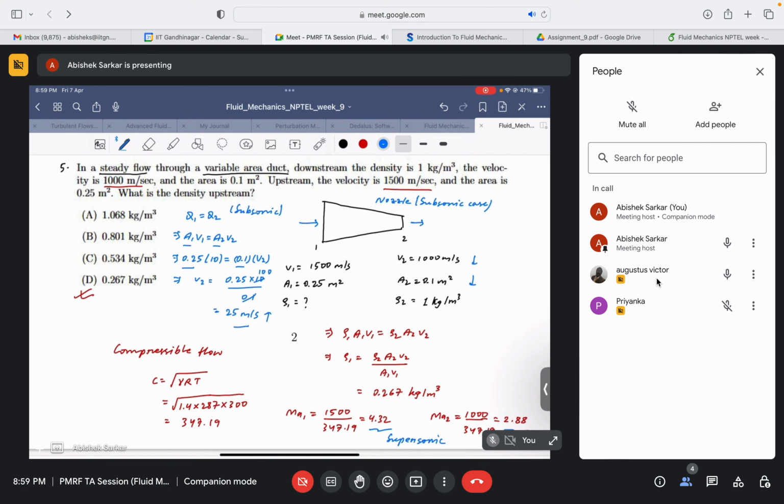The change in density is appreciable, very much appreciable in a supersonic case, which overcompensates the usual flow pattern that we observe in the subsonic case, and which essentially causes a reduction in the velocity even if the flow passes through a nozzle. And that's why for a supersonic case, this acts as a diffuser.